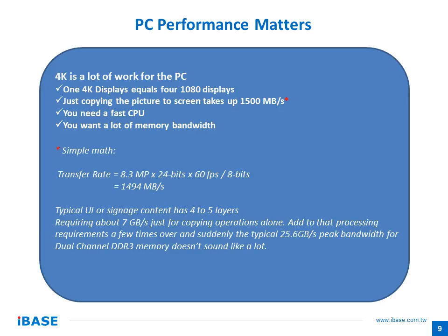We're not even talking about decoding the content, doing an overlay, performing any effects, doing any processing, or anything like that. So realistically, you need a factor more in terms of memory bandwidth just to cope with the read and write cycles that will happen when you drive 4K content through a PC. So memory bandwidth is very, very important.